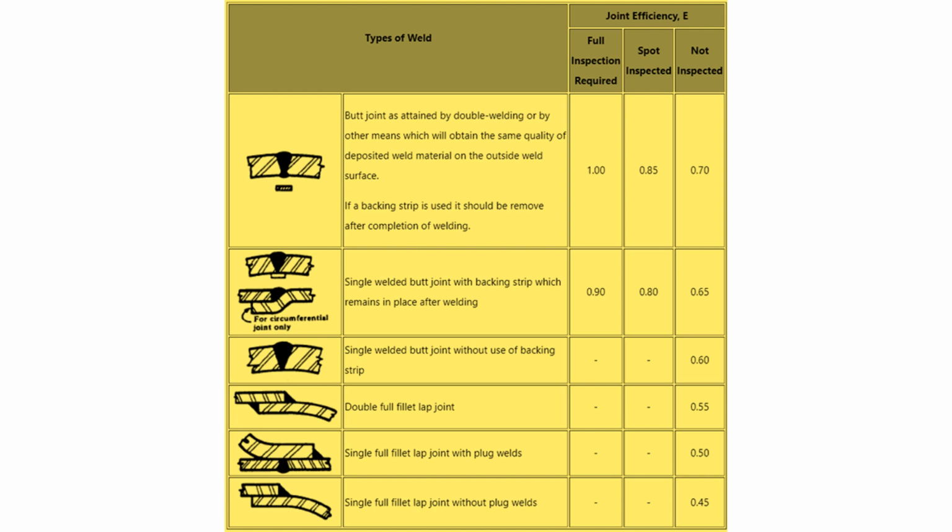And normally, whether it's a pressure vessel with high pressure or low pressure, we always go with type 1 welding. Why? Because wherever there is a butt joint, you always go with type 1 welding, and the radiography is done on the butt joints. It cannot be done on the fillets or on the nozzle, only on the butt joint. Wherever the butt joint is there, we do radiography.